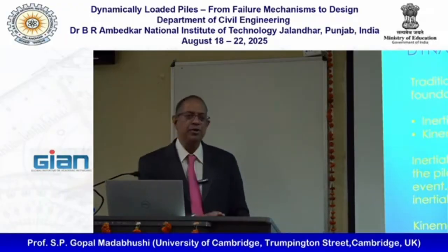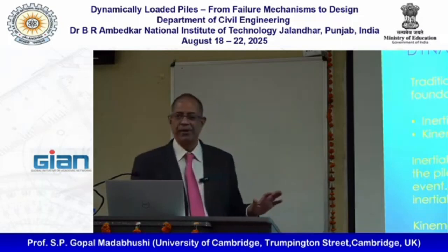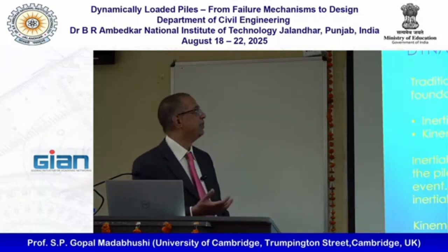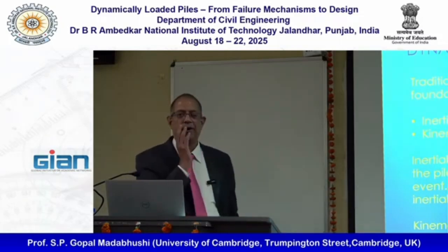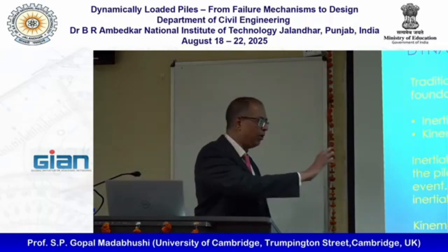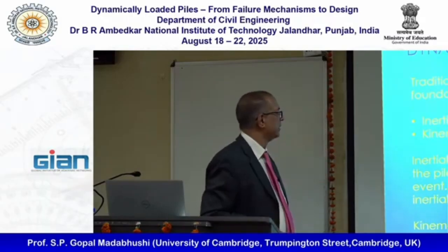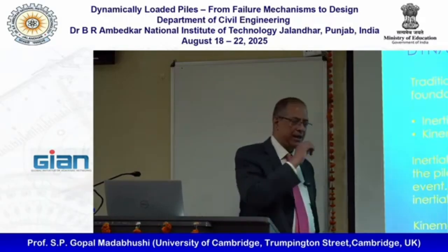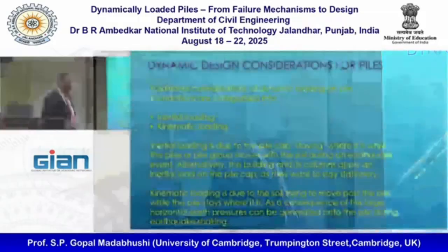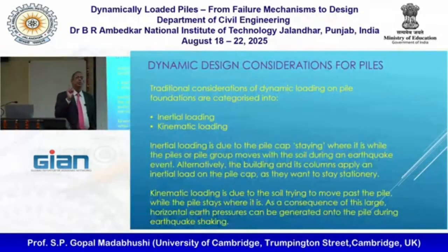Right. Now we want to move away from that and look at the dynamic design considerations for piles. All we have done so far is static. The first thing about piles and dynamic loads is that there are two types of loads a pile will attract. One is called inertial loading and the other one is called kinematic loading.